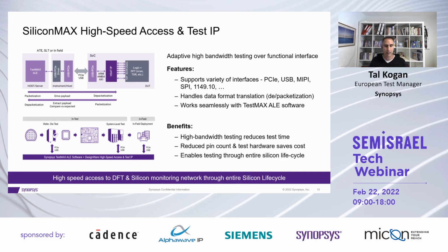In turn, that would have a great effect on your test time, because it would affect the length of the chains or channels that you use, and then the length of the shift, of course, which dominates the patterns. So all of that translates into the number of channels you might have in your system, which is a great benefit.